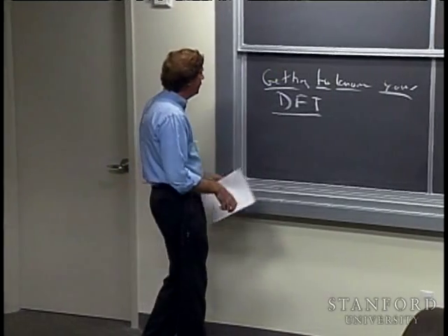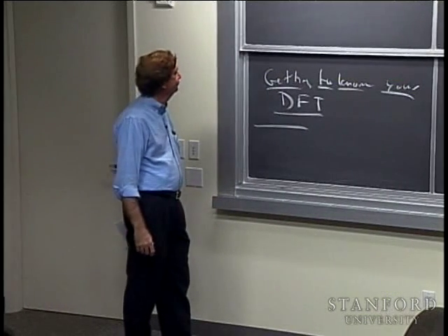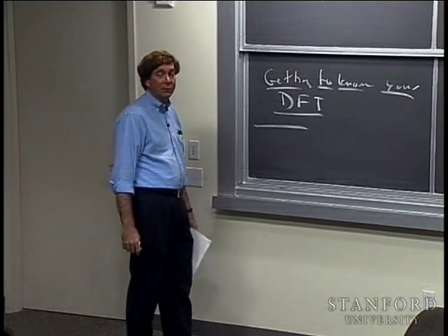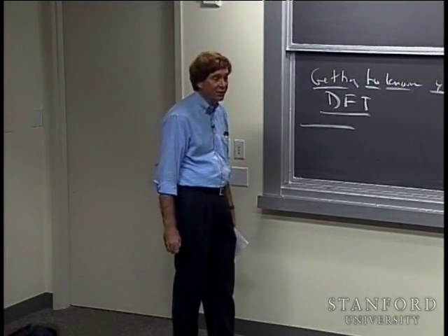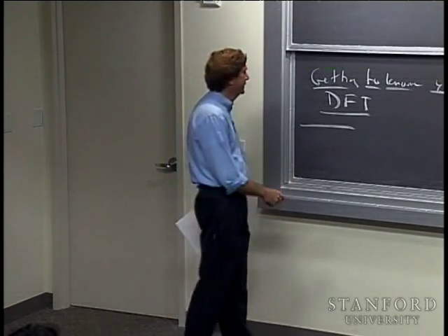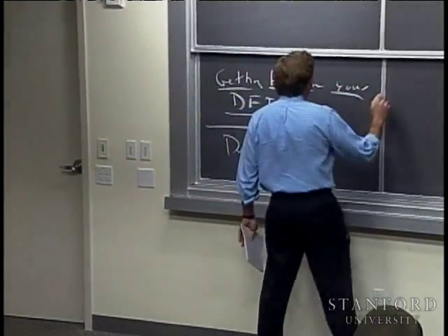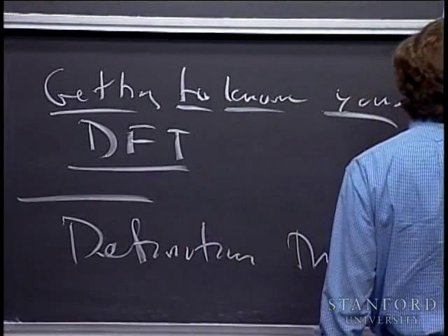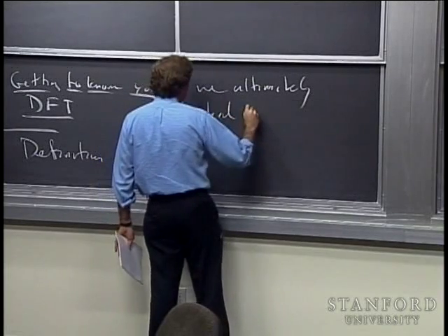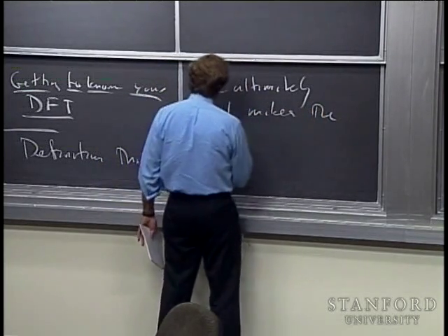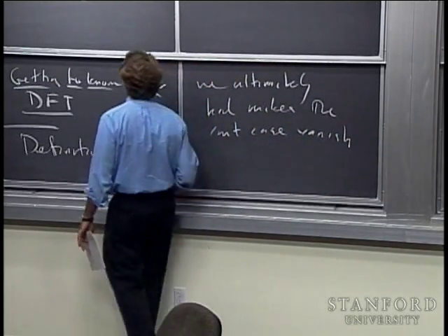All right, now, before doing so, let me recall the definition. Here's the definition, and where we ended up last time was a definition where the continuous case, the idea of sampling a continuous signal to get a discrete signal, sampling its Fourier transform to get a discrete Fourier transform, all that had pretty much vanished by the final definition. So the definition that we ultimately had makes the continuous case almost invisible, vanish. It looked like this.